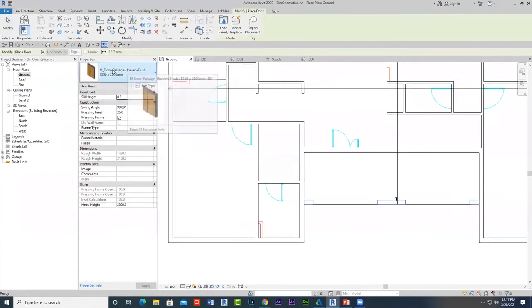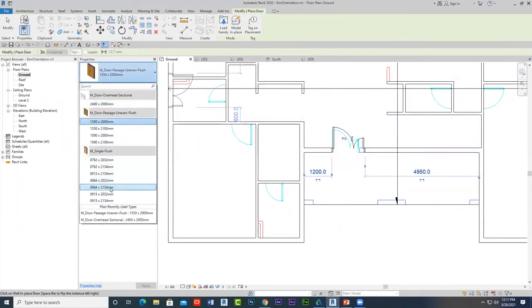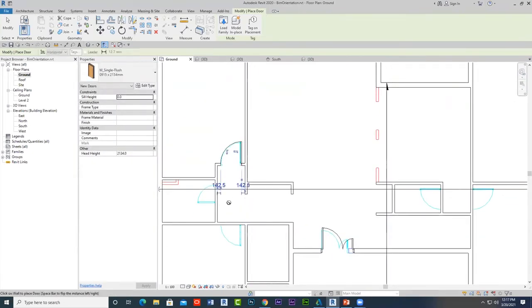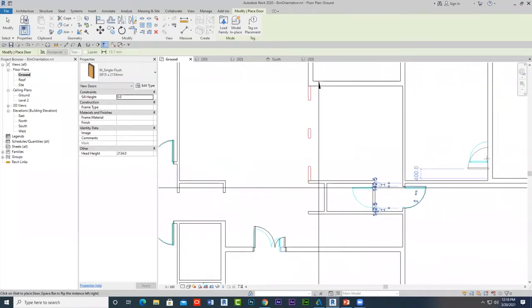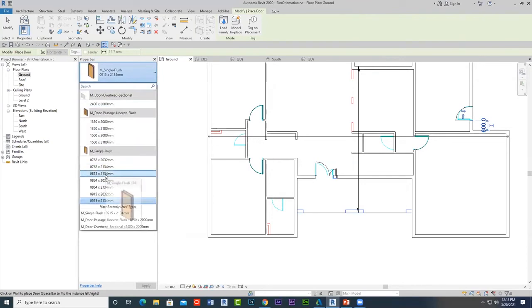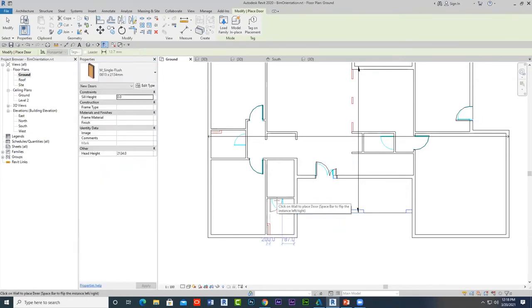Let us place windows. Without going into too much detail and specific sizes, this one, as seen, is good for the entrance. This one can be used for the bedroom area. The wall, when clicking on it, will automatically make an opening, while clicking the spacebar will reverse the action. By choosing a smaller window that can be used for a WC now, like this one, by clicking on the spacebar.